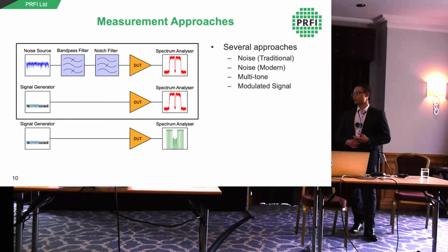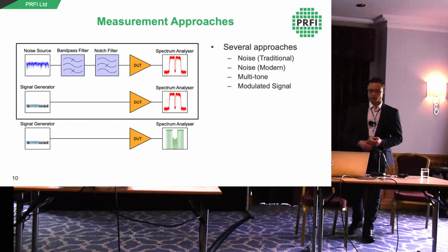More recently, you have signal generators that are capable of generating the full NPR signal. That can be a noise signal, as you see there. That could be a multi-tone signal, like we saw in simulation, or some signal generators will generate the full modulated signal and create the notch for you. So if you wanted more applicable NPR results, you could do that. Though that wouldn't, strictly speaking, be NPR, and it wouldn't quite be as generalizable. But you have that option sometimes.